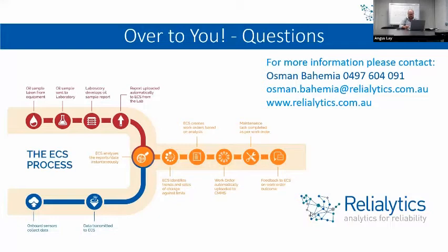My only recommendation on that, and this is coming from my lab background, is that laser particle count is probably not the best method. Typically a patch method is better, because in new oil you've got additives that haven't actually dissolved, which can register higher than typical particle counts, higher than what you would consider a clean oil for that particular compartment type.